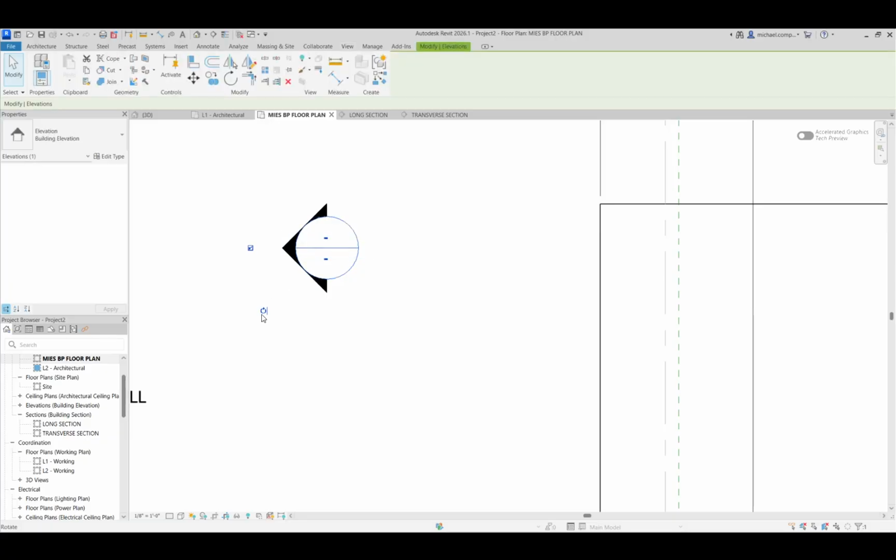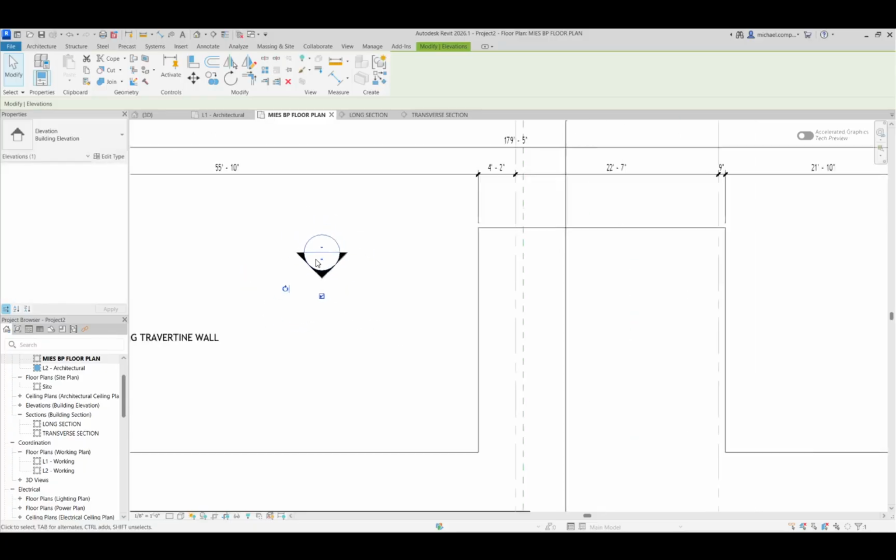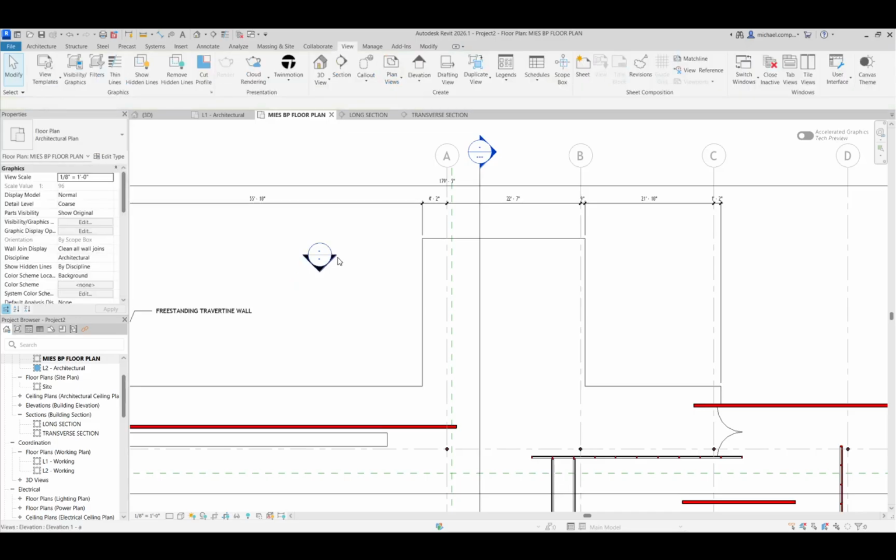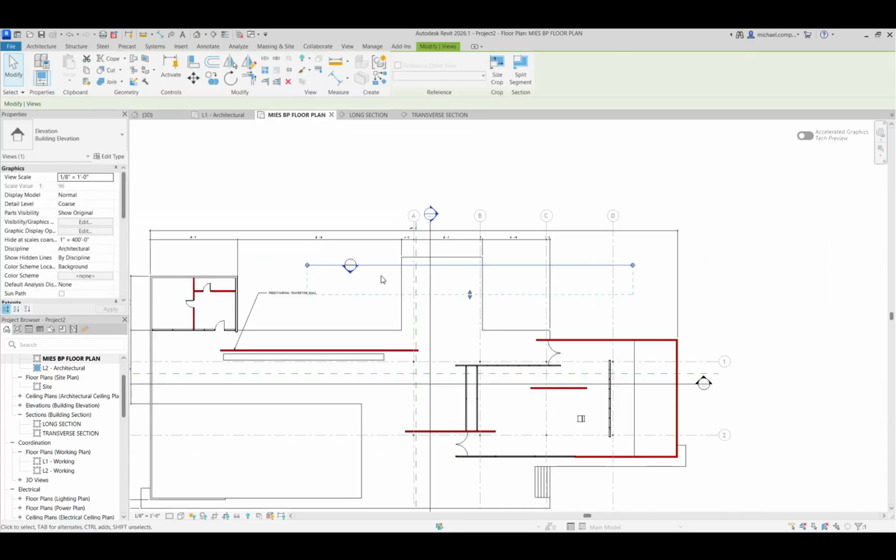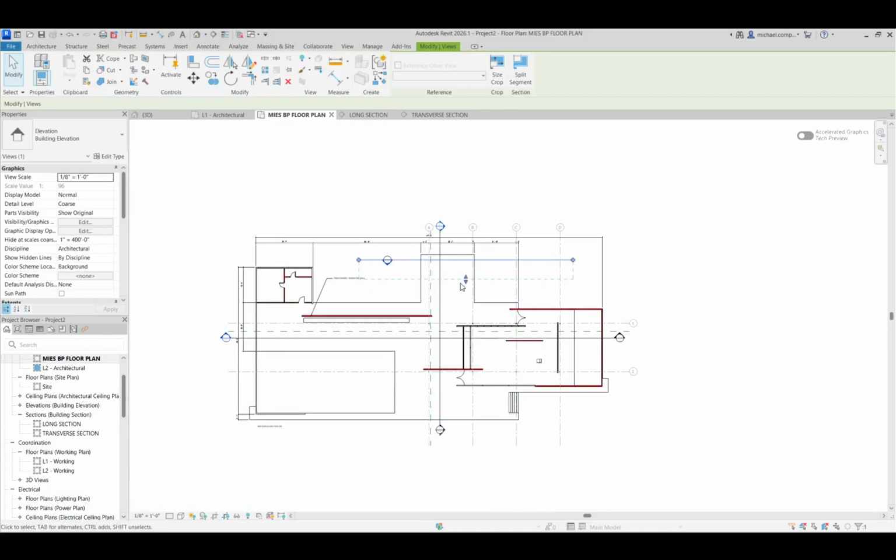Yeah, select the circle, and then hit this little rotate and pull it down, and now it's looking the way I want it to look. I'm going to select the arrow and notice what is in the scope, right? So if it's an elevation view, I want to get all of this stuff, and then I want the extents of it to cover the whole model, right?